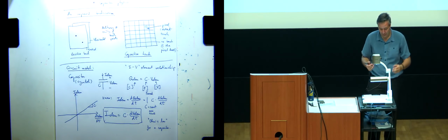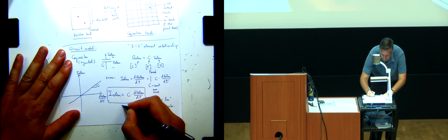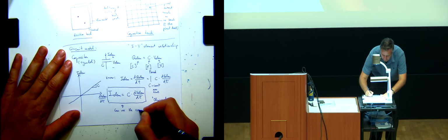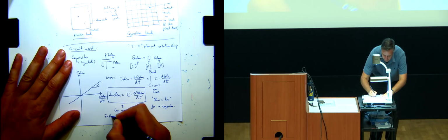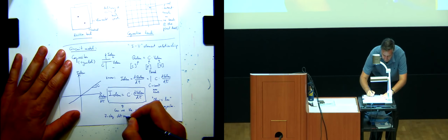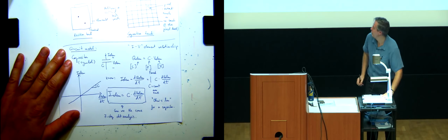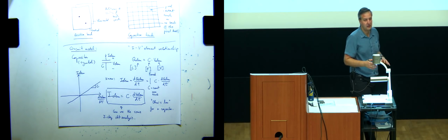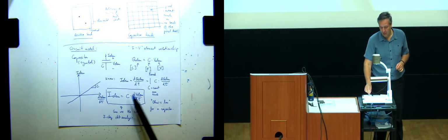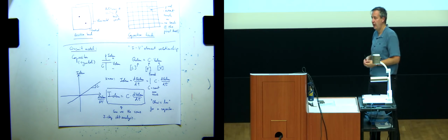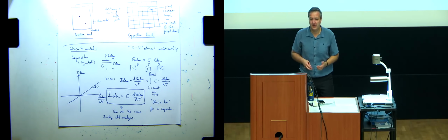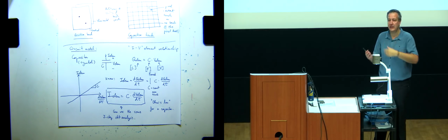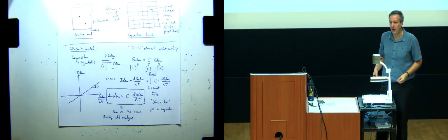And what's beautiful about this formula is that you can use the same 7-step circuit analysis. All I need to do to reuse all the knowledge that we have in circuit analysis is to replace in my equations the voltage of the element with a derivative of the voltage on the element. Everything else stays the same in the 7-step analysis. And we're going to do a few examples so you can see how this is a completely okay thing to do.